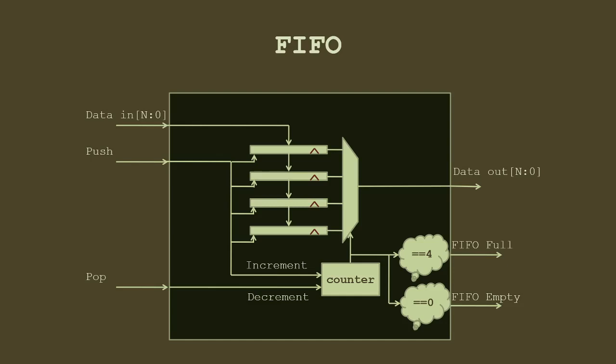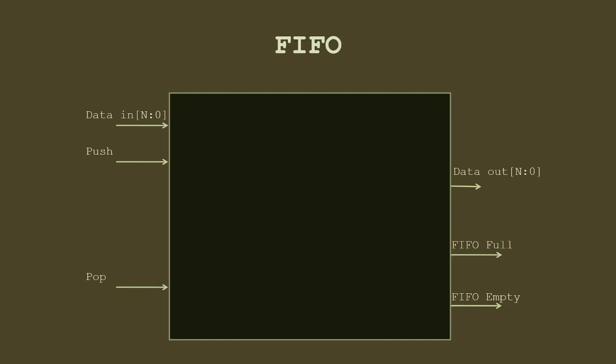So you have to come out of this mentality of writing software, because Verilog is a language, but it's a hardware description language. Whatever we write describes hardware. So I've seen codes where people have written spaghetti code that runs in simulation but doesn't run on FPGA because they haven't gone through the design process correctly.